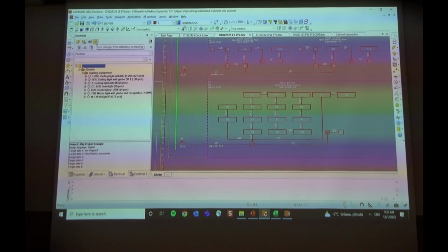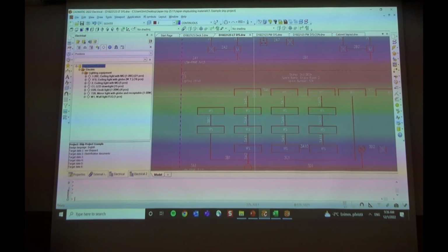We had them on the arrangement drawing and also the single line drawing. We now can see that these updated here. So we have now this 1FS here. The symbols all changed at once. We can see on the tree now that we have 16 of these 1FS models and only 21 of these others. So the amounts automatically update. Database, records, project tree, all there, everywhere. And also the 3D model.